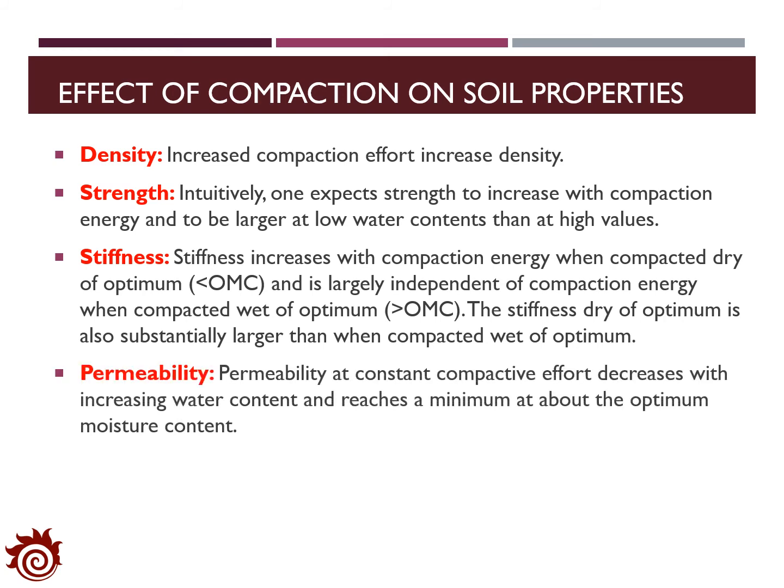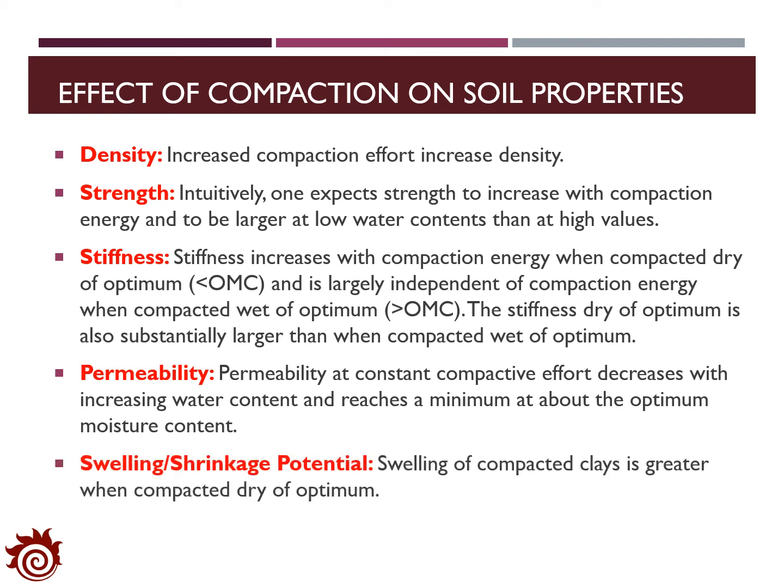For the permeability, we can see that the permeability of the soil at a constant compactive effort decreases when we increase the water content, and usually it will reach a minimum value at the optimal moisture content. Finally, the swelling of compacted clay is greater when compacted dry of optimal.